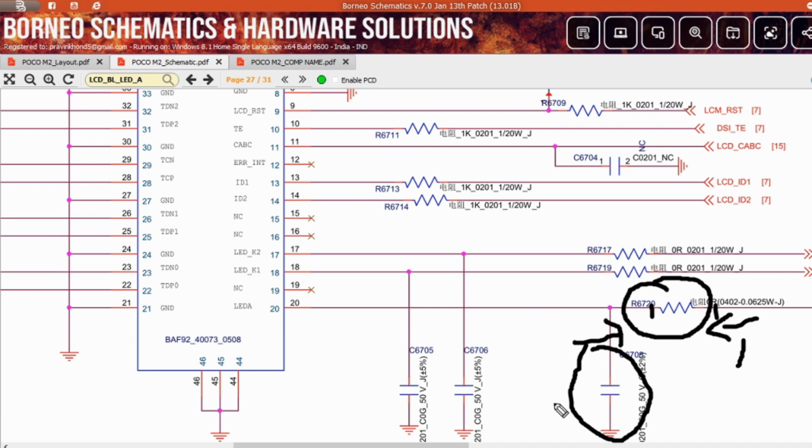Sometimes you will see there is no capacitor or any component on this line besides a resistor. After the resistance you can see filter caps, but between the display connector and this resistance there is no capacitor or any component in a parallel line. So how is this line short? Because you measured and confirmed that this line has a short, and a diode value on this point, confirm.